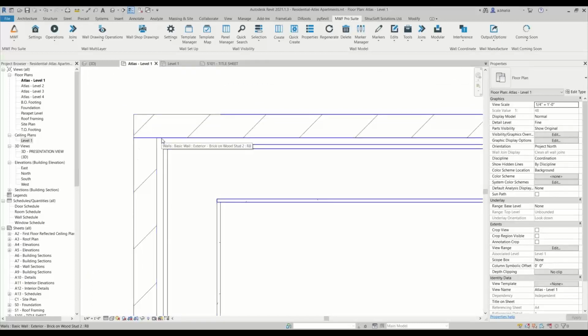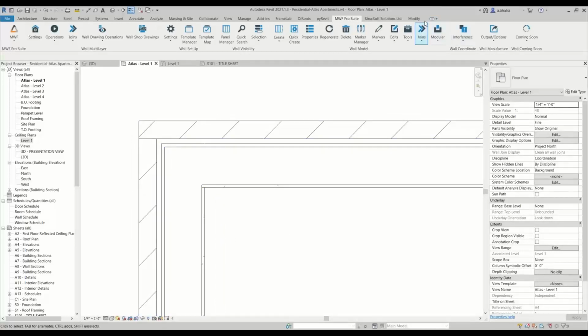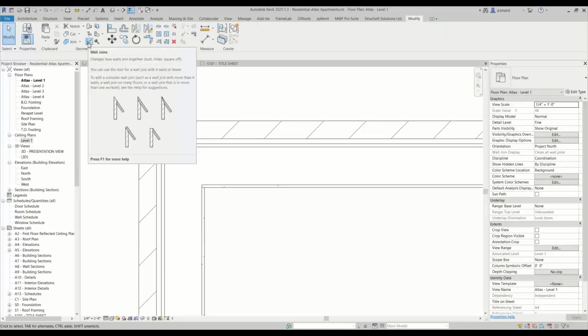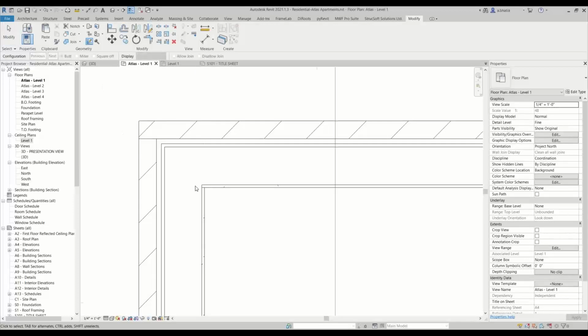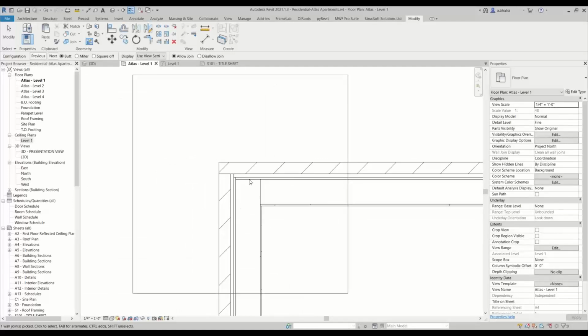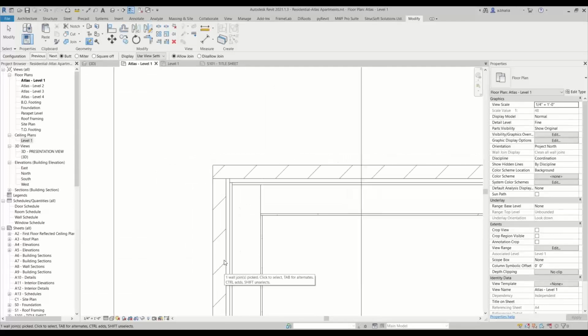So that's how Revit can make sure you have a clean join, if you actually have your finishes be even, basically. The other way you can double check is you can sometimes get a clean join out of these conditions as well. When you take a look at the join geometry here, you can actually see which one's considered the main wall. Right now, this one's considered the main wall, but at the same time, it's cutting short here. So if I wanted to see what the next preview was, this is how the preview would be.